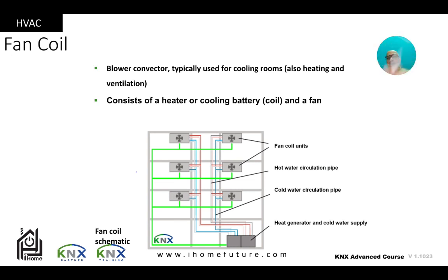Now we are talking about fan coil. Fan coil is a different concept because we don't have just a valve, but we have the hot or cold water, plus we have also a fan connected to the system. So most of the system is based on hot water flowing in the pipes or cold water flowing in the pipes, depending on whether I use it in a heating way or a cooling way.